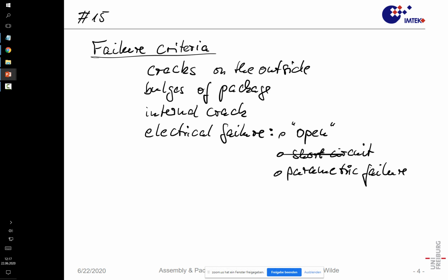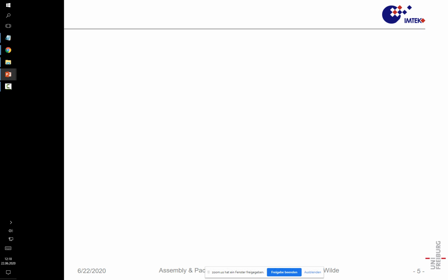So that's, you could say, something like a very big shock in the beginning of the device's lifetime, and that could already lead to some damage, which becomes apparent in later tests. And so this initial soldering with a standardized profile is not only in popcorning important, but also in many other reliability tests.